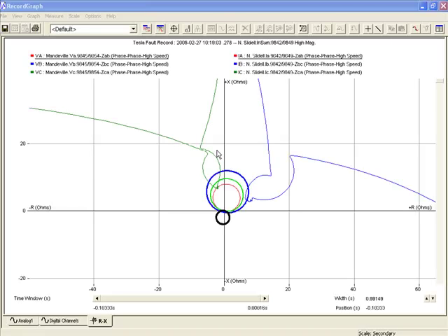In this section, I'm going to show you how to create an impedance diagram, and at the same time how to plot the impedance fault trajectories from a record captured by a Tesla 3000 fault recorder. At the same time, you can superimpose your distance relay zone settings into the same impedance diagram. One of the advantages of plotting my impedance fault trajectories along with my Mho circles is to determine whether or not the distance relay issued a trip on the proper zone.